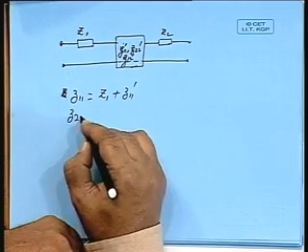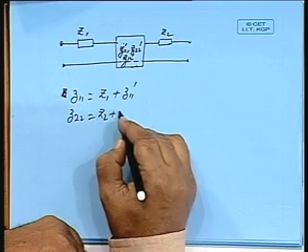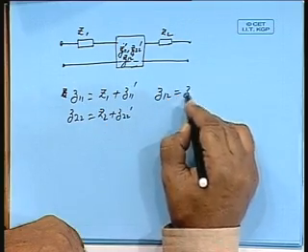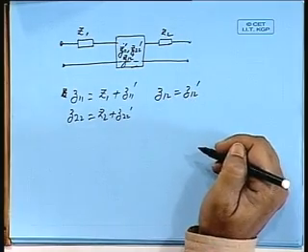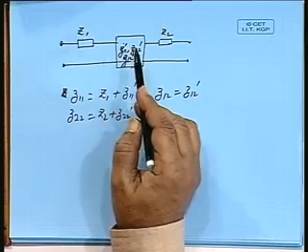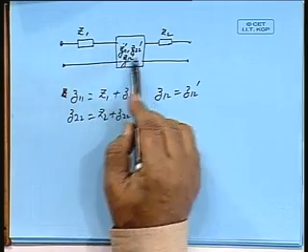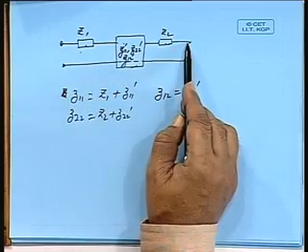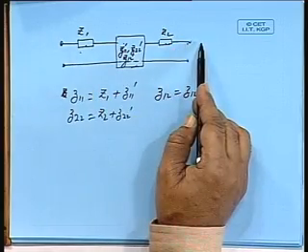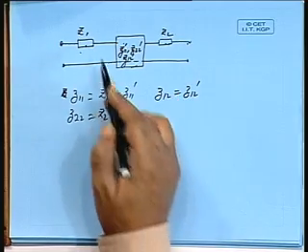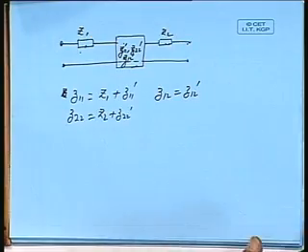Similarly, Z22 will be Z2 plus Z22 dashed, but Z12 remains unchanged. Okay. So, once again the private poles of an impedance set can be removed as series elements in the respective sides. So, this is the series and shunt separation of private poles.